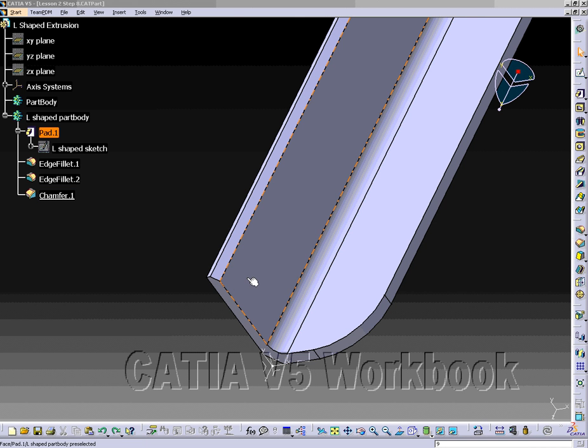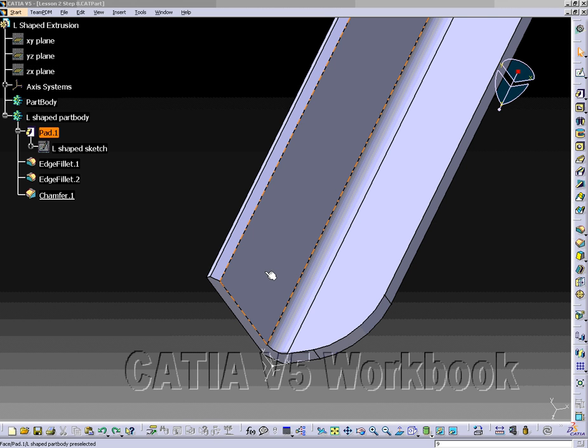Before the hole can be created, two edges need to be selected. The two edges are required to correctly and accurately locate the holes. The surface the hole is located on will also have to be selected. The two lines in the surface can be selected at the same time by holding down the Control key as you select the line and surface.